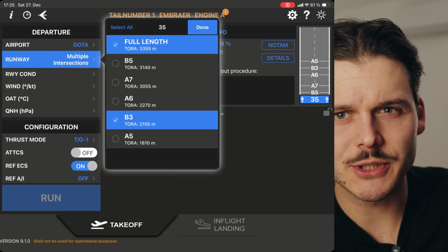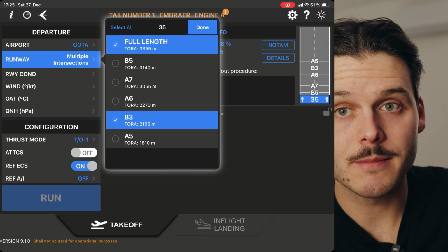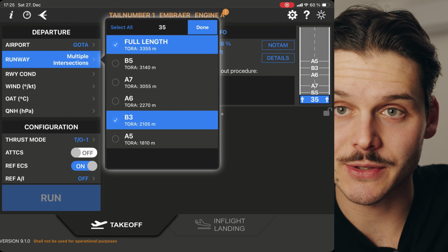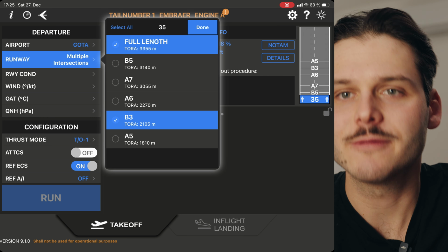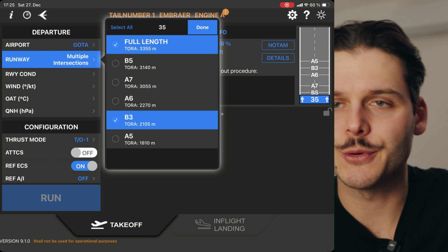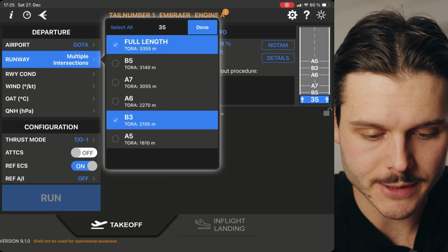There's a good saying in commercial aviation: as safe as commercially possible. So that means that, of course, it would be safer to have 4 engines on an aircraft, because if you have one engine failed, you wouldn't even notice it too much in cruise. But 2 engines is just much more economically feasible. So this is why we do it.